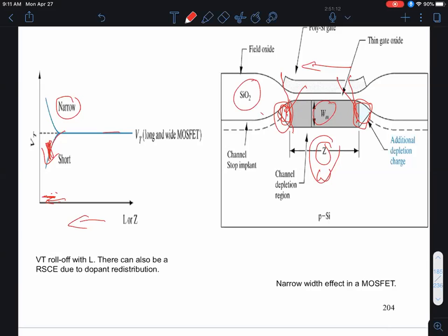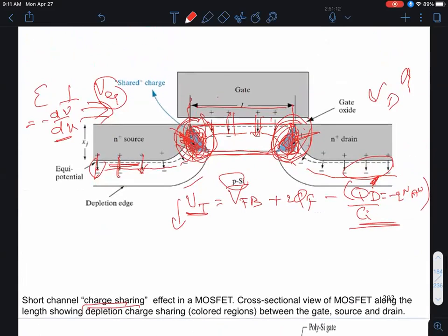These are the isolation regions. Okay. So this is an example of what's called low-cost isolation. Okay, where you grow a local oxidation to have a very, very thick oxide. And the reason for having a thick oxide, if you remember, is in the expression for the VT, the CI, which is the dielectric constant of oxide divided by the thickness of the oxide, becomes very low. So if D, the thickness of the oxide, goes up, CI goes down, so this final term goes up, and VT increases.